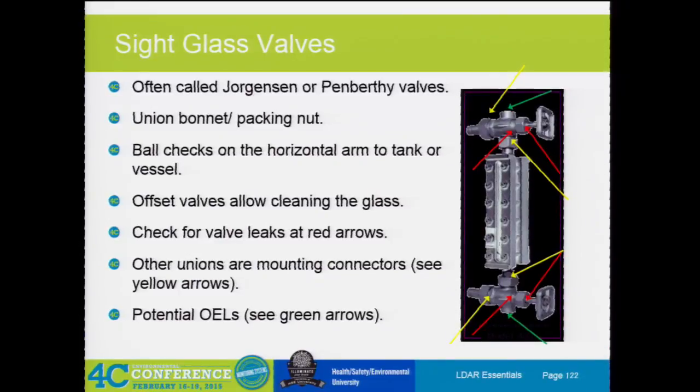Some plants actually treat those top ones and the back side where it ties in as connections. Do you guys treat that as part of the valve or as connections as well? Yeah, those are usually treated as connectors. So the only real spot you monitor is where the stem comes out of here, and this right here, where your packing would be in there.